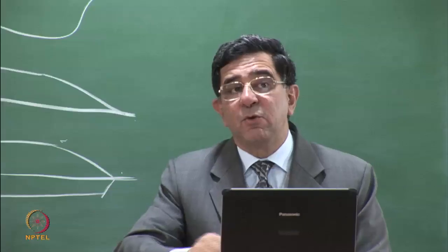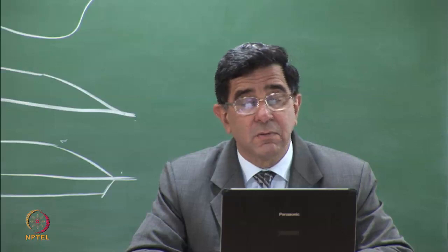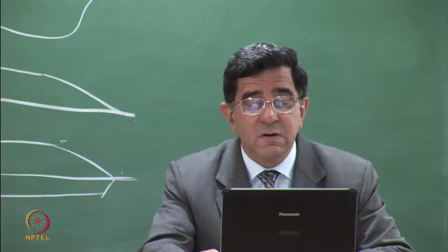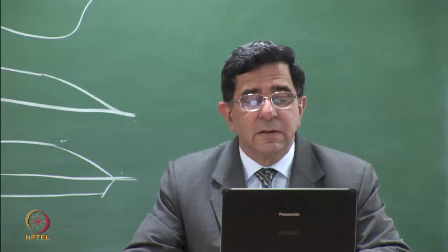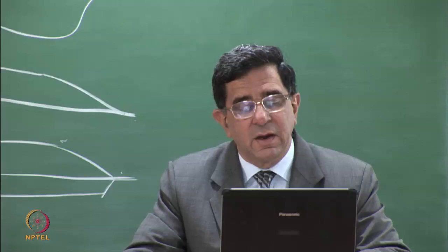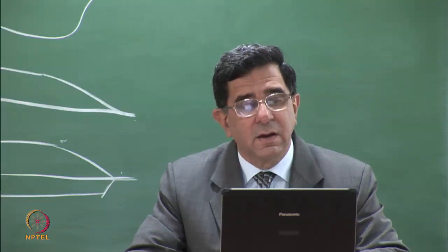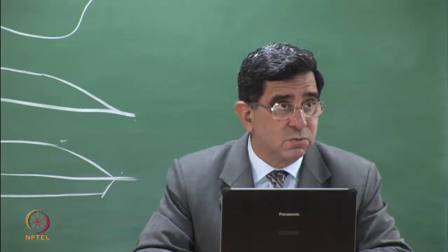There is often an attempt to economize on the number of wells, and an alternate arrangement where you can reduce the number of wells is this. Here I put a well here. All the leachate from here will come here, and all the leachate from here will also come here. The distance to travel now is a little more, but there's only 1 well instead of 2.